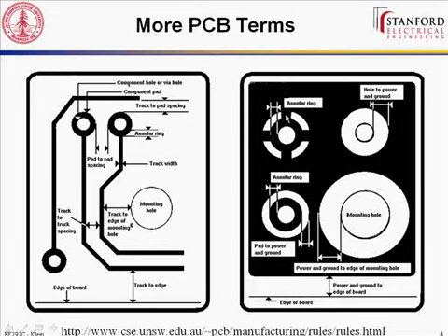But since we have these tiny spokes going off, and these are generated for you automatically, this is not something you have to do, you only have to heat up basically the annular ring plus some gradient across these spokes before you can solder, so it's much easier. If you do not have these thermal reliefs, it's nearly impossible to solder. Trust me.